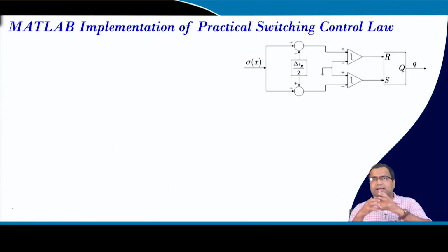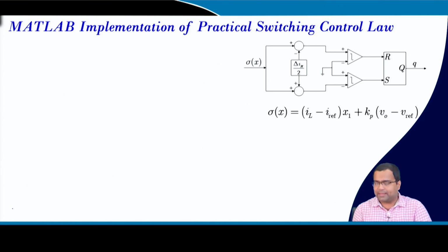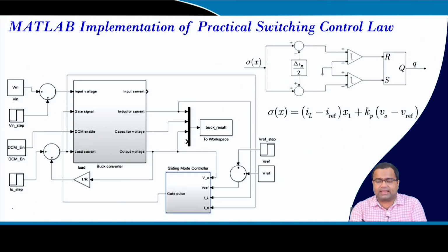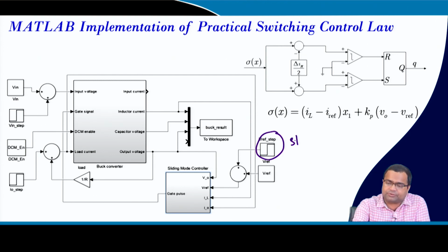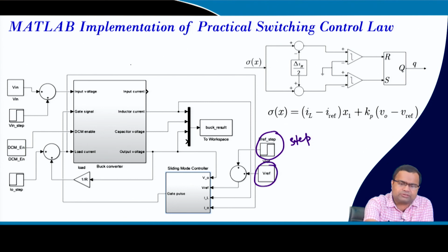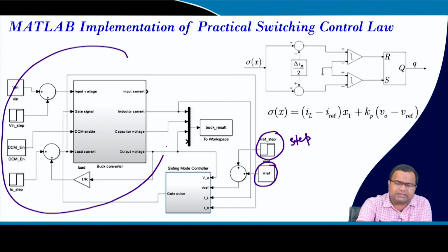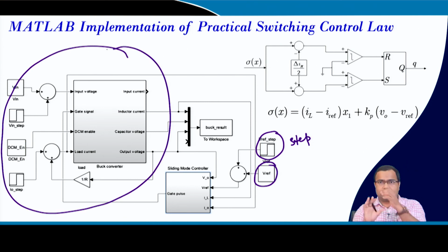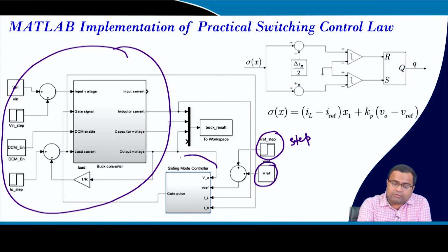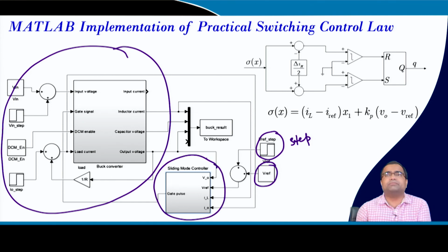I did it a little differently in MATLAB. Here again is a sliding mode controller, and this is my reference voltage, to which we can apply a step for the step transient. I am taking the output voltage. This block I have presented multiple times, so it is known. We are going to discuss how to implement this controller.